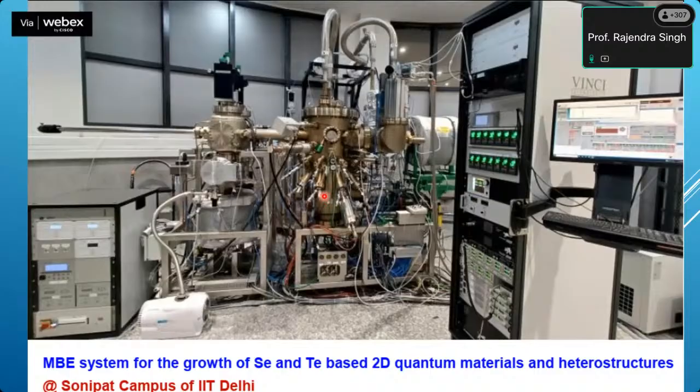The material is embedded inside this K cell, and when you heat it, it will evaporate. So it is a kind of physical vapor deposition. It will go in the form of a molecular beam, something like light coming out of a torch. That's why it is called molecular beam epitaxy. This is the viewport from where you can see how the growth is happening.